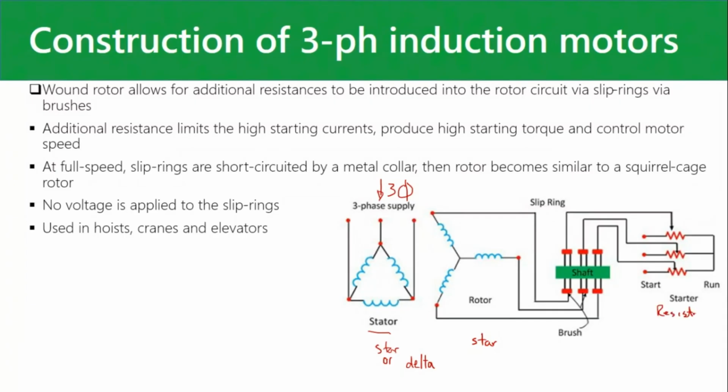So what happens with this R per phase is connected. If you follow this line like that, you see it's in series with the phase impedance of the rotor. So if this is R plus jX over here, the impedance of this one phase, then you simply add this resistance in there and you do your calculation like that.